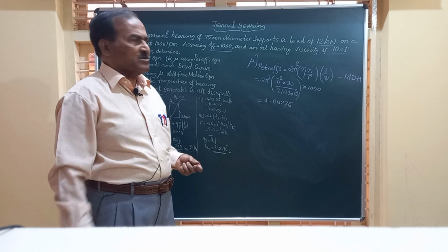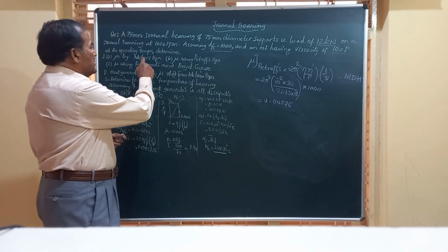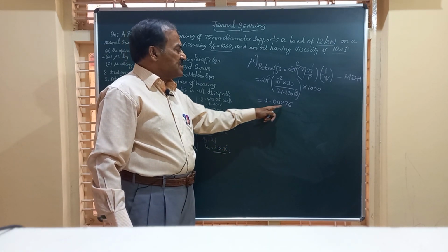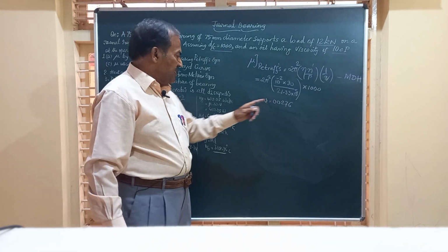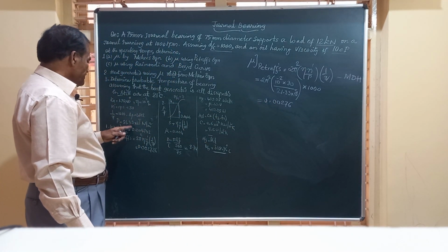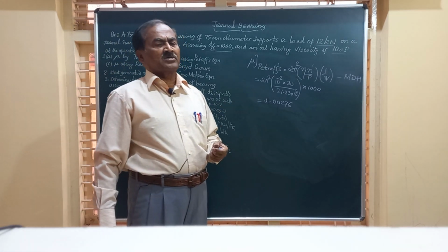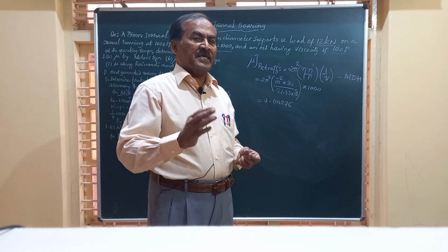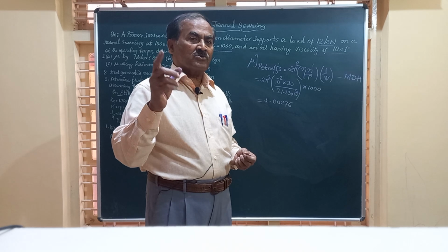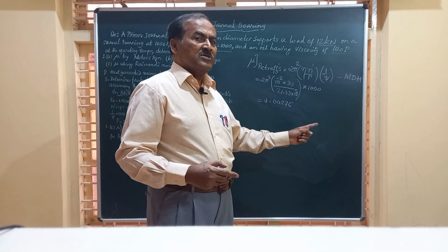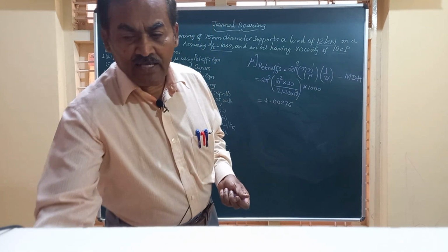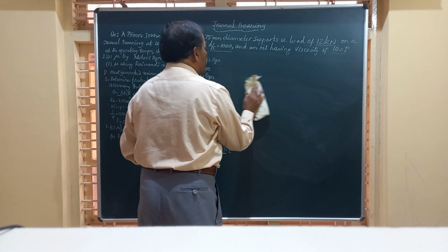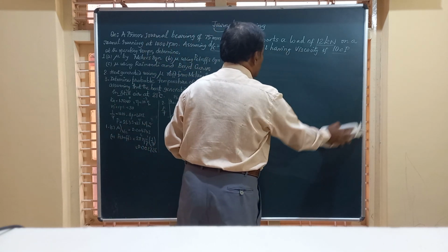And friends, if you just observe the value of mu obtained by Mackey's and that of Petrov's, approximately the difference is 0.002. Here is 0.0476 and here is 0.00276. So Petrov's equation does not take into account the effect of end leakage, which is 0.002, and hence you are getting a value slightly lesser than that obtained by Mackey's equation. So we have found out the value of mu using Mackey's equation in part A.